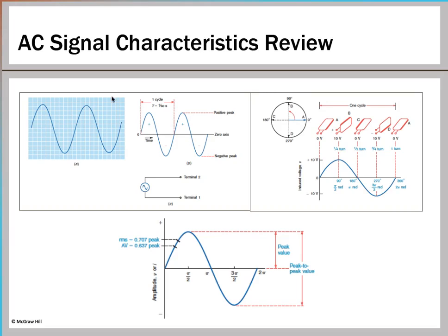Whereas for current measurement, you first have to turn off the power, disconnect the circuit wherever you want to measure the current, connect the ammeter, turn the power on, and then do the measurement. So that's a long process. Compared to that, measuring the voltage is much easier.